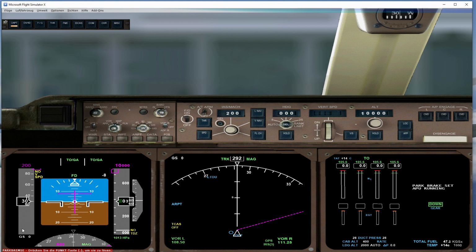Okay, then you check here if there are any flags, like if the flight director is not working, you get a yellow indication with an FD inside, so that means there is some issue with the flight director. But of course today everything's fine. Well, the nav display takeoff is off because we're still at the gate. Which just means that at least the airport is shown. Because we check data as well. Some data like speed restrictions will be shown at the waypoints as well as the ETO, estimated time over. The position shows you the current position of the different navigation systems, like from VOR or from different IRS. But in the simulator it's just perfect, so you're right here.